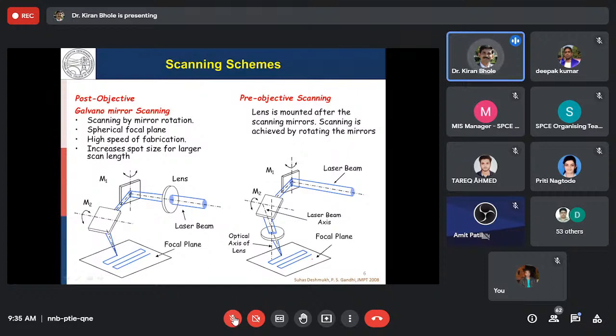Again, it is logical that the focus point will not remain constant on the free surface of the resin. As it is not constant, the focus spot is uniquely present at only one point, and at all other points it is a defocus point. Because of this, again there is a resolution problem and a curing problem that may happen.